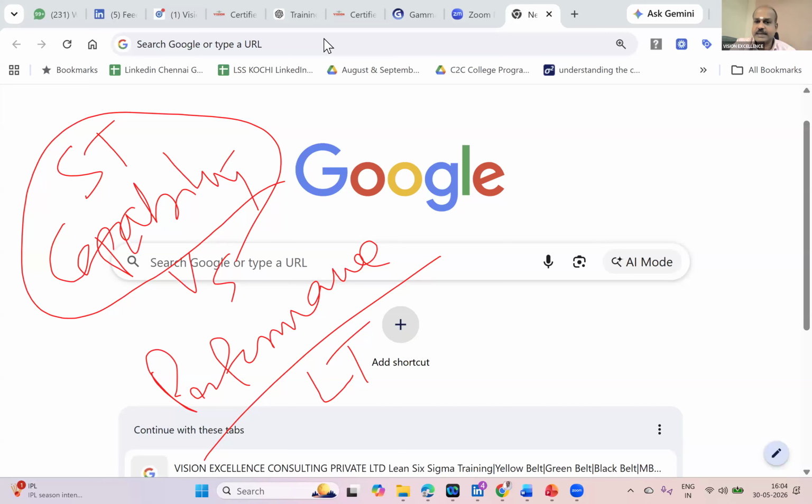For example, as time passes, right now you remember all the discussion, isn't it? If you sit in an interview tomorrow, you will be very happy discussing CP and CPK because you just learned today. But if the interview happens after, let us say, 6 months, then the tendency is to forget. Yes or no? Similarly, the performance also tends to deteriorate over time. As you move from short term to long term, the PP and PPK will always differ from CP, CPK with a lower value. First thing.